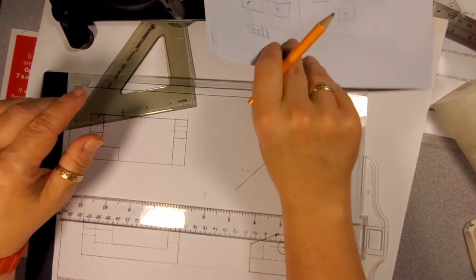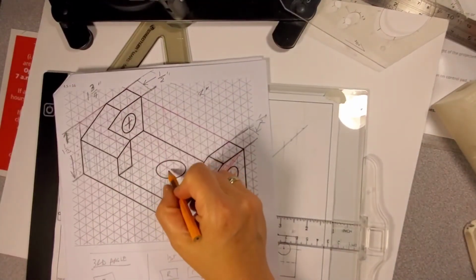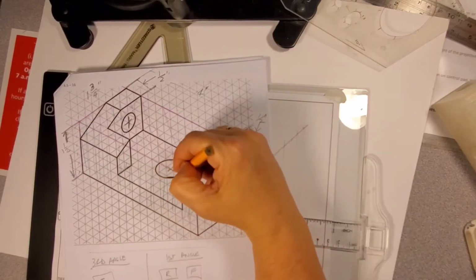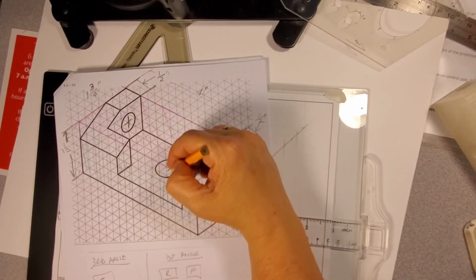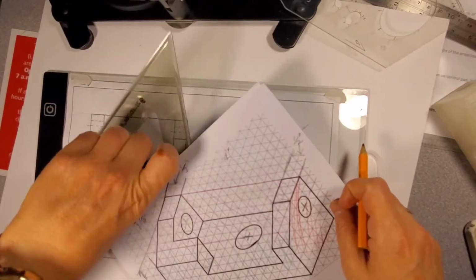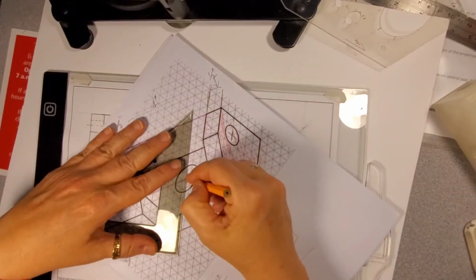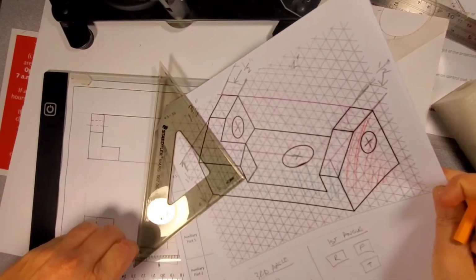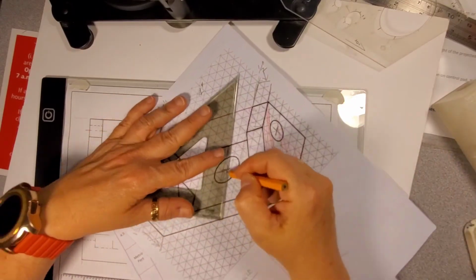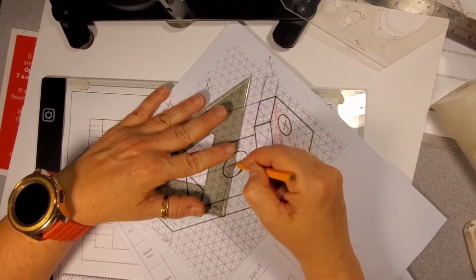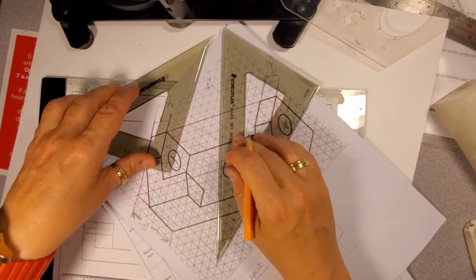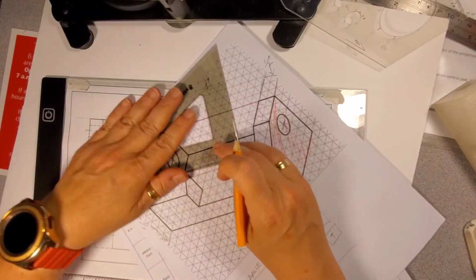Next, we've got this hole. Now this guy's a bit of a pain in the Badinsky because its center is actually centered to one of the squares. Did you notice that? Man, your teacher is such a pain in the butt. Badinsky, excuse me. So how do you measure where this thing is? My method for figuring it out is I'm going to line it up. This is set to 30 degrees, so I'm going to cheat and use my 30-degree triangle.